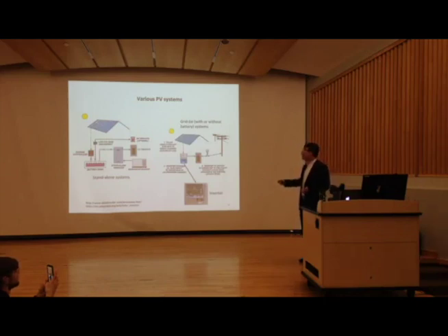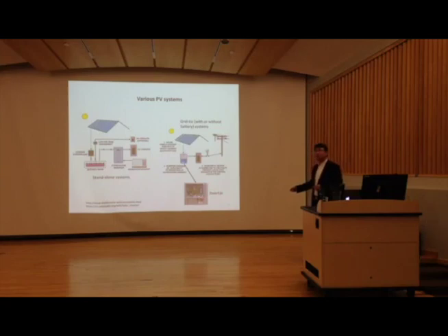But for most cases, people use this other type of system. You have to tie the electricity generated from PV panels onto the grid. We call it the electrical grid. The way it works is first you have to convert DC into AC. The major electronic equipment to do that, we call an inverter. If you go by some house with PV panels on the sidewall, you may see something like that. That's the inverters. Of course, after the electricity passes through the inverters, you're going to have 110 volts AC current, and then you can directly connect that into the grid.